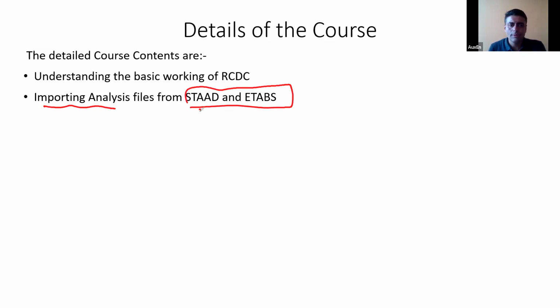As I told you earlier also, importing the analysis file from STAAD is easy. It's a one-step process because STAAD and RCDC are from the same Bentley systems, but bringing the analysis file from ETABS to RCDC can be a little bit challenging. It will be a multi-step process because RCDC is not compatible with ETABS, as they are products of two different companies. So we'll see how to bring analysis files from STAAD and ETABS.